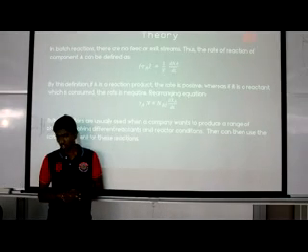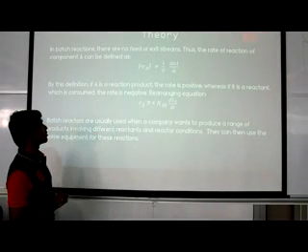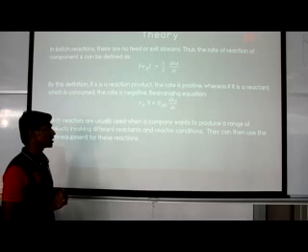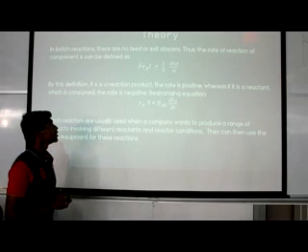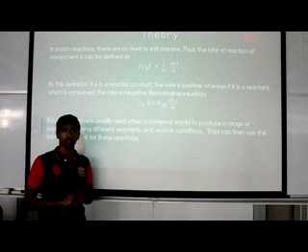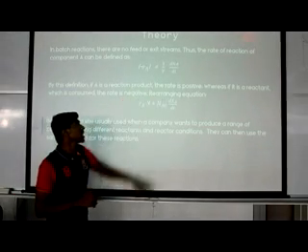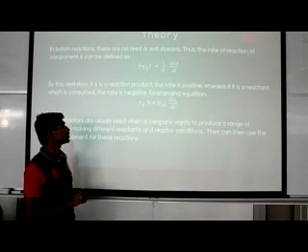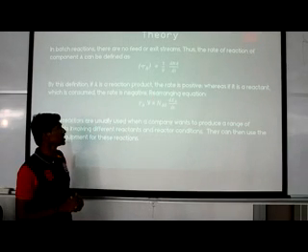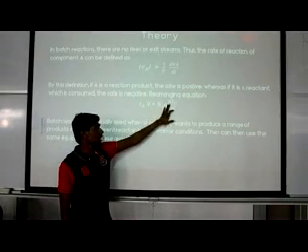Next, now I'll talk about the theory about this experiment. As you can see here, in the first part of this slide, I've mentioned that there's no feed or exit stream for batch reactors because it's not a continuous flow. So from the general mole balance equation, in minus out plus generation equals accumulation, we will get this equation here, whereby the rate of reaction times volume, from generation, equals the accumulation. Rearranging the equation, we will get rate of reaction times volume equals NA0 dX over dt.